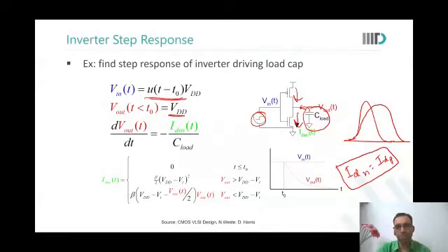So if V is changing, I know that for this particular period, my PMOS will be on, my NMOS will be on. But this V out is because of C load. Because of this, I'm not able to say at what time my PMOS will be in linear or saturation. So this kind of current, I won't be able to say.